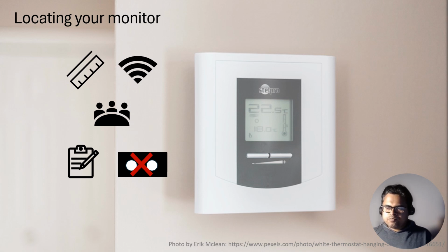Maintain a distance from pollution sources within a room. Make sure you place the sensor where there is good connectivity. I mean, do not put it inside a box or near a microwave, which can disrupt the signals. Put it in occupied spaces with free airflow and at about breathing height. Don't place it where people are not likely to be, like in some corner where no one is ever going to be.